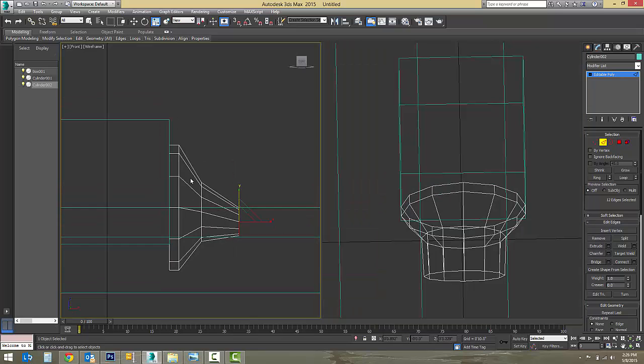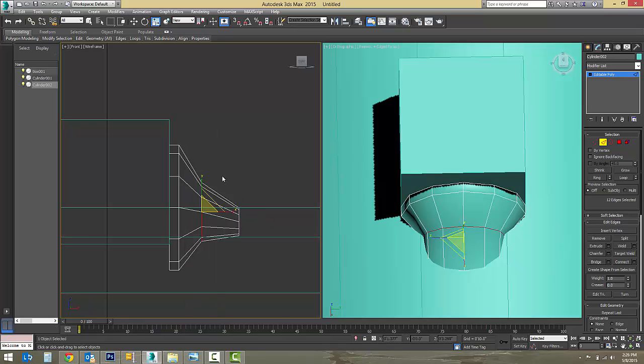And this is jagged and I don't want that, so I'm going to grab this one center thing and hit Control, right click, chamfer, and I'm going to add a little bit of extra mesh in there, and that'll smooth it out. I'm also going to grab this edge and add a tiny lip, and that'll make it less jagged.